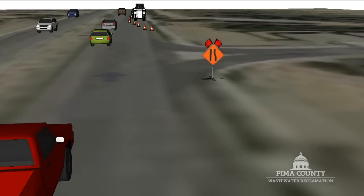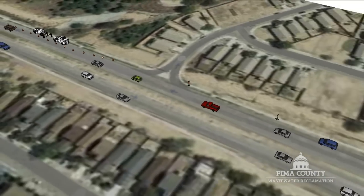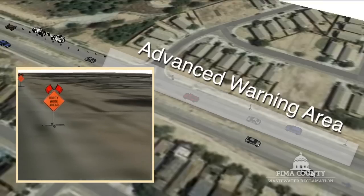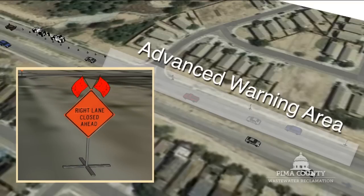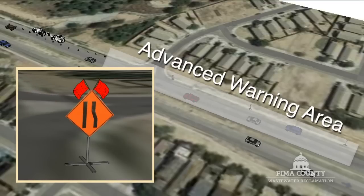There are 5 components of temporary traffic control setup for high volume traffic. The advanced warning area is the area where drivers are informed of what to expect ahead. RWRD Conveyance uses 3 signs for the advanced warning area in high hazard setups. The first sign tells the drivers utility work ahead. The second sign will inform drivers which lane is closed ahead. The third sign is the universal symbol sign to assist with any language barriers.